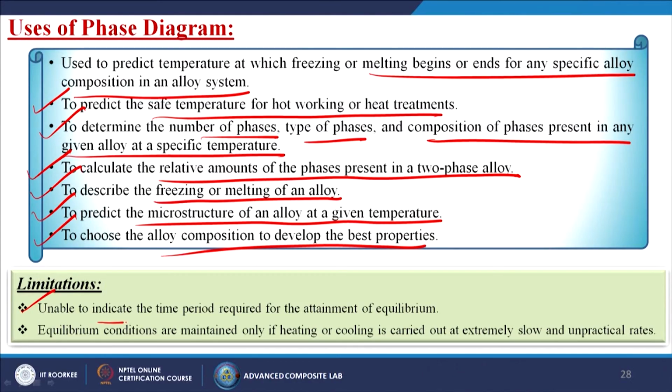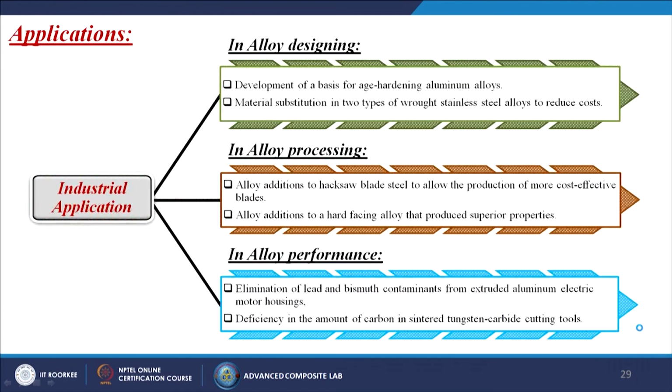Yes, but of course there are certain limitations. What are those? Unable to indicate the time period required for the attainment of equilibrium, and equilibrium conditions are maintained only if heating or cooling is carried out at extremely slow and impractical rates. Now what are the applications?